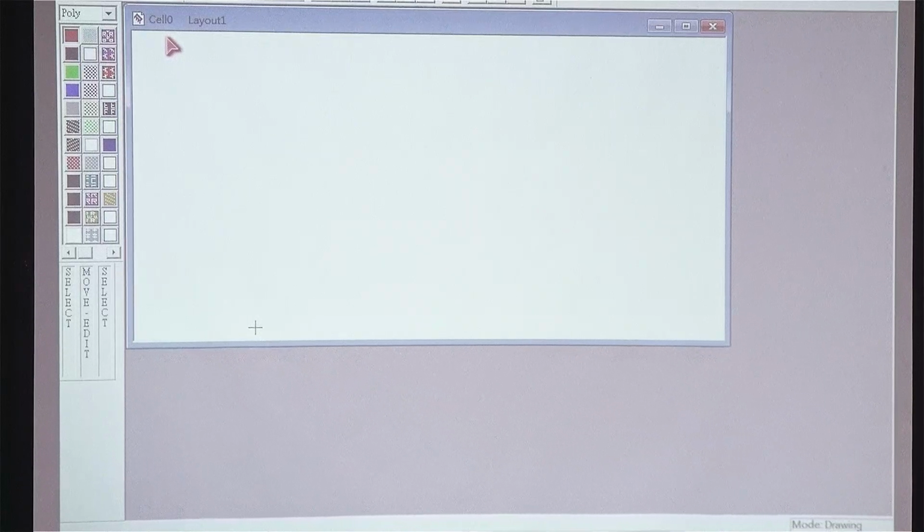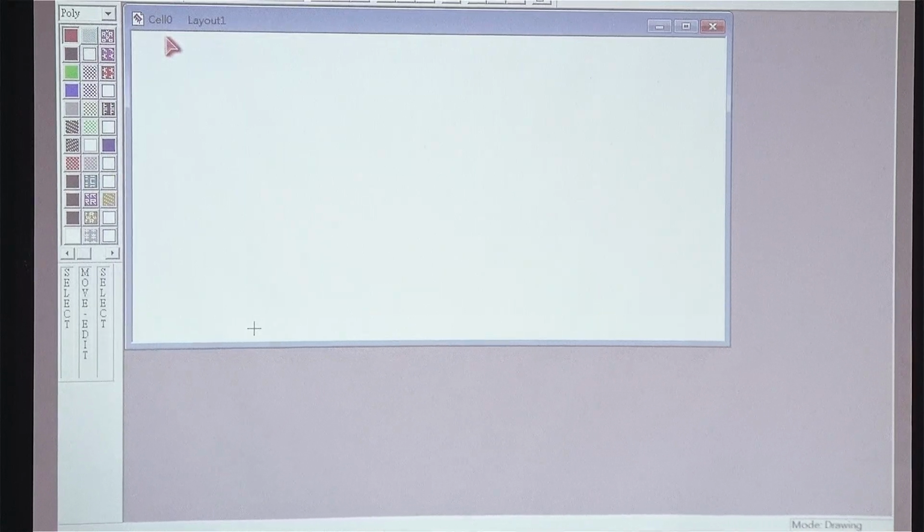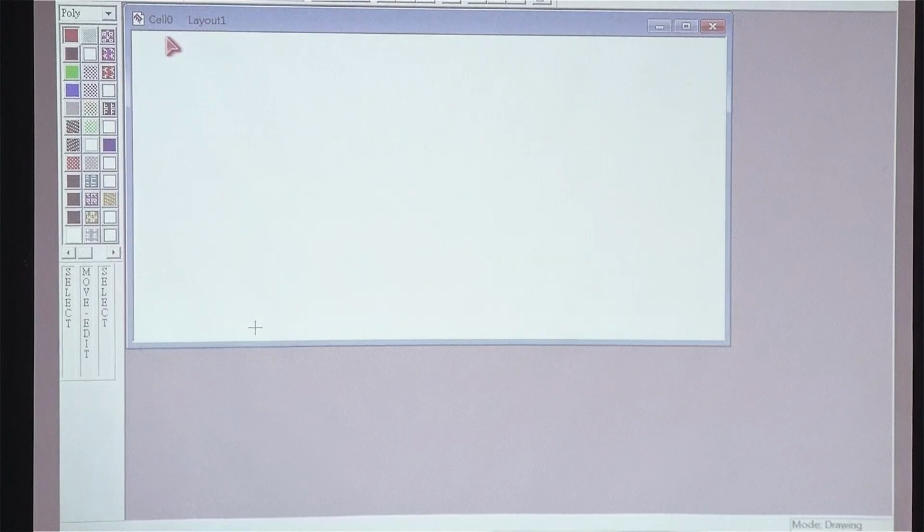For different cells you can design different structures, different devices over there. There's a number 6, cell name, layer name. Then number 7, layer name. The layer name is shown here. Currently I select poly, it's poly 1, and if I push here, it becomes poly 2. This is poly 2. This is active area.